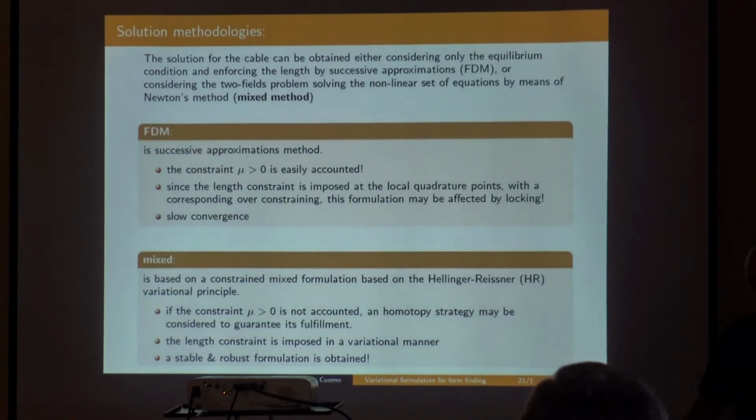Now, solution methodologies. Typically, the force density method has been applied adopting a solution strategy which is done by successive approximations. As I told you before, we assign something initially, then some force density, and we correct it iteratively in order to enforce the constraint we want to impose. So this is what is typically done with the force density method.